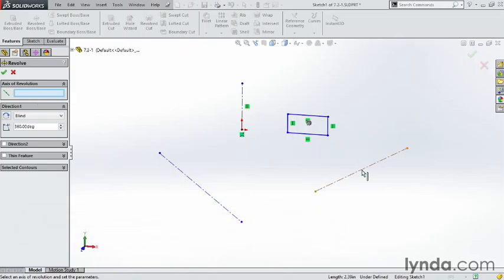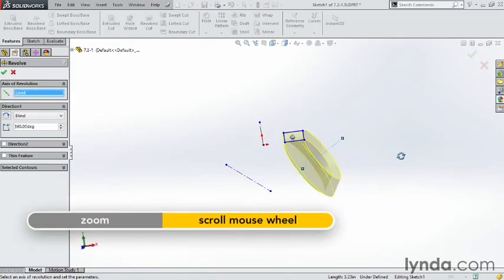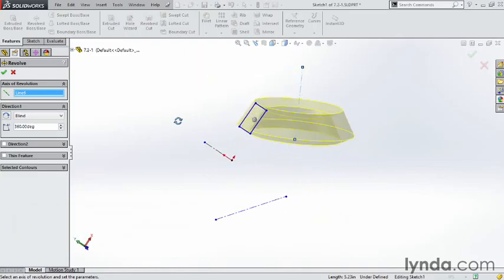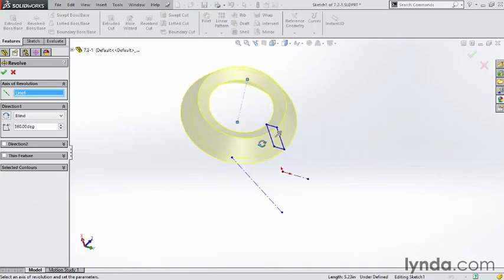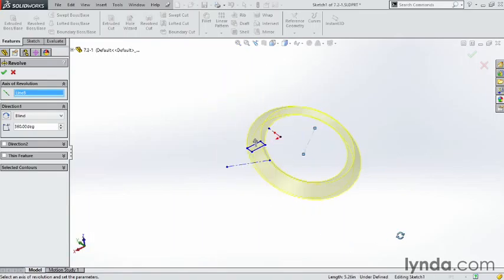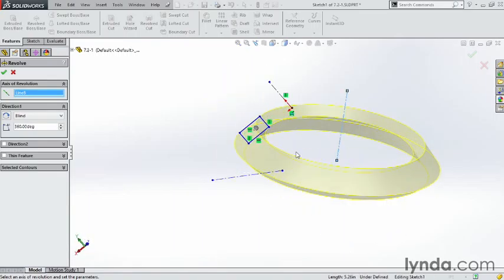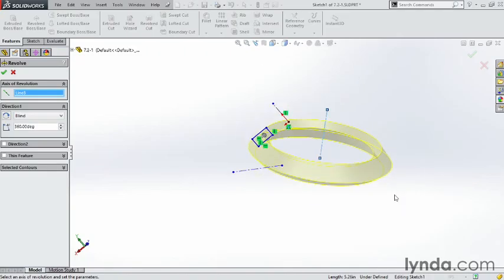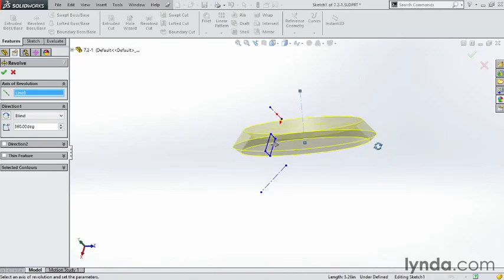But if I wanted to change, for instance, instead of line 5, I could delete that out of there. How about this line over here? Notice I'm taking that same simple rectangle and rotating it around a different line, but this time I'm getting a much more complicated shape just by changing the axis of rotation. And again, if I got rid of this line here, I could do it around this line as well, and get a much bigger shape, similar to the last one, but more complicated. It's just a simple rectangle going around an axis, just not perfectly straight, so it's giving this interesting cone-looking shape.